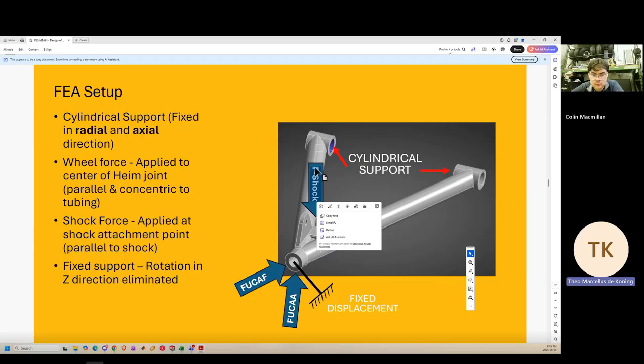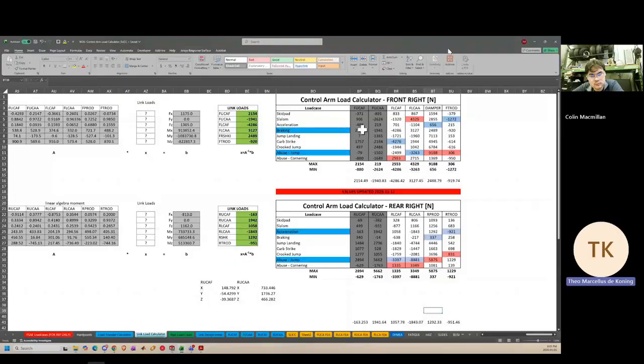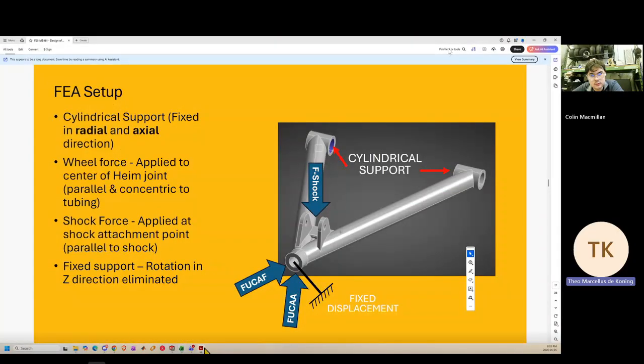It's combined loading, right? Because you have tension compression, and then you have your shock load as well. Right. Yeah. So these are grayed out because you shouldn't directly use these. You have to do some extra math. Our assumption of treating these as 2-force members is, I wouldn't say 100% correct, but it's good enough.